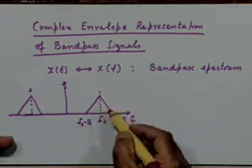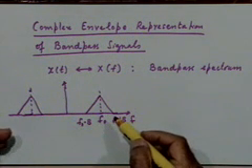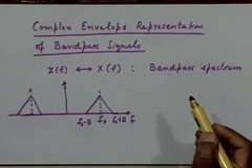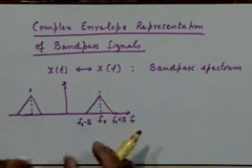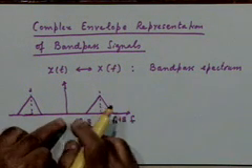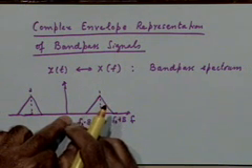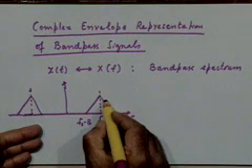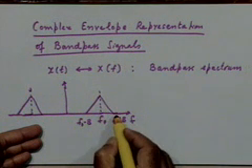There is no particular significance of this symmetry. They don't have to be symmetrical. What is required to be symmetrical is that the spectrum should be even symmetric around 0, right? That is the required property of the spectrum of a real signal. But there is no symmetry requirement around the center frequency that you may want to define. I could as well have defined the center frequency anywhere in this band.